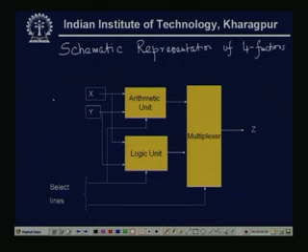So, this X is a 4-bit bus, Y is also 4-bit, and this is the arithmetic unit. Again the output is a 4-bit bus, this is F, it goes to the multiplexer's 0 line. Then the logic unit, again 4-bit, and it has 2 select lines because it has 2 levels of multiplexers, S0 and S1.